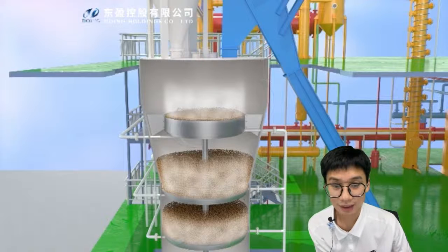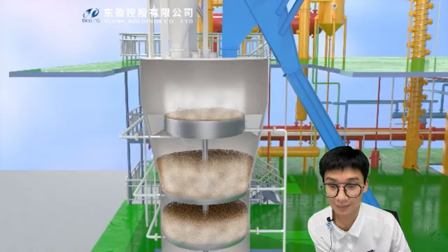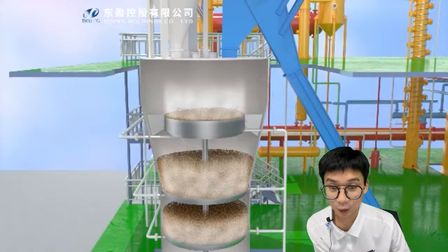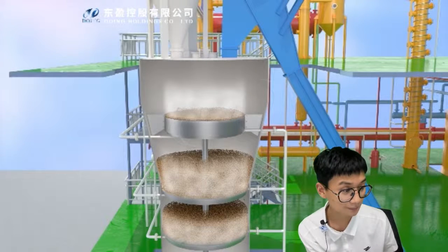The preheated meal enters the self-steaming layer, in which the wet meal is in direct contact with the mixture of solvent steam and water steam from the lower layer, and the heat of the mixed steam is used to heat the wet meal. The indirect steam in the bottom interlayer of the desolventizing layer is also used to heat the wet meal, and the multiple layers of the desolventizing layer are set to give full play to the self-steaming effect.